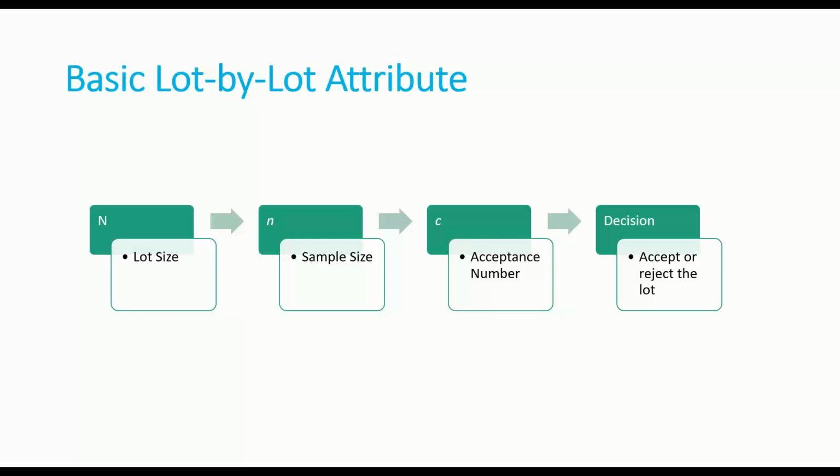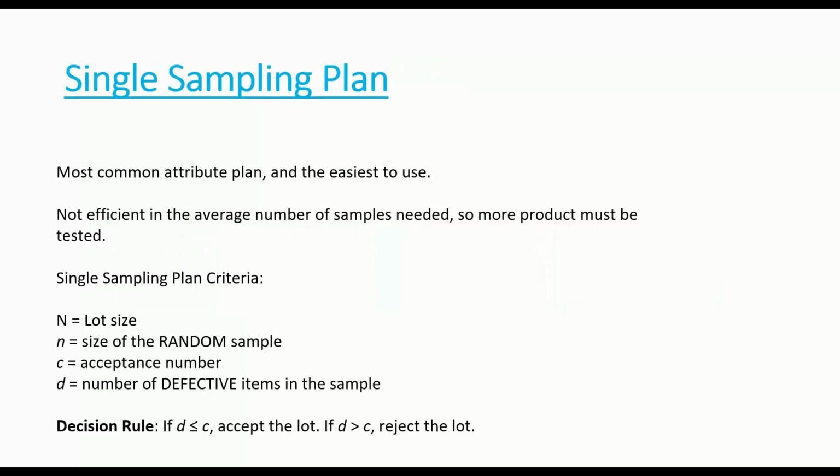And usually that's the rectifying inspection, where you replace all the defects that you found, and you go through and look at 100%. And as you're going through and looking at them, as you find more defectives, of course, you're going to replace those too, until you've looked at them all and nothing in there is defective anymore. Okay, so this is the simplest one, the single sampling plan. It's the most common. It probably answers most of the questions you'll ever have about sampling for attributes, the go, no go kind of yes, no things.